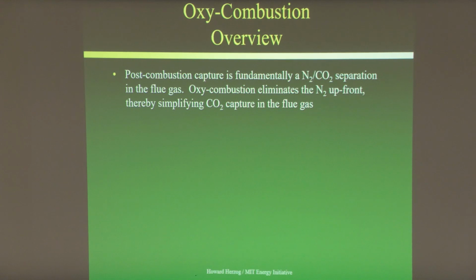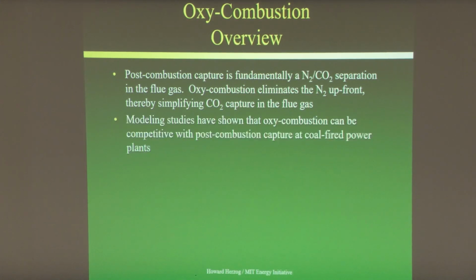Oxy-combustion capture, basically what we're saying here is we have our flue gas is a nitrogen-CO2 separation, but if we can take the nitrogen out before the combustion process, then we have pretty pure CO2 coming out the end. There's water vapor with it, but that's easy to separate. But now we replace the nitrogen-CO2 separation from the flue gas with the oxygen separation from air up front.